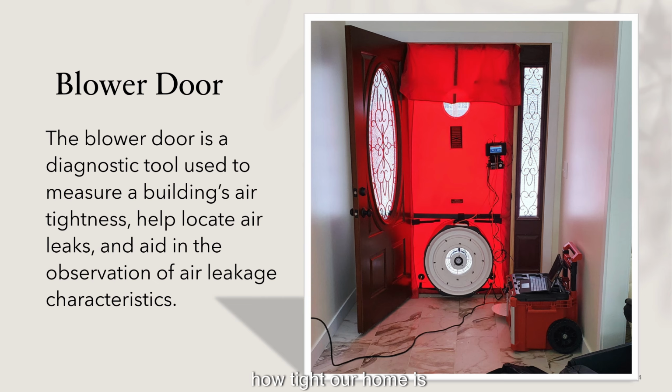It's a very simple test to determine how tight our home is. Remember those 5 characteristics that we talked about, the loose, semi-loose, average? That's how you determine how tight a home really is. We have to do a blower door test. Sometimes we can do our due diligence. We just know the codes and what a semi-loose home looks like or a tight home looks like. But to really know for sure, we're going to do a blower door test.